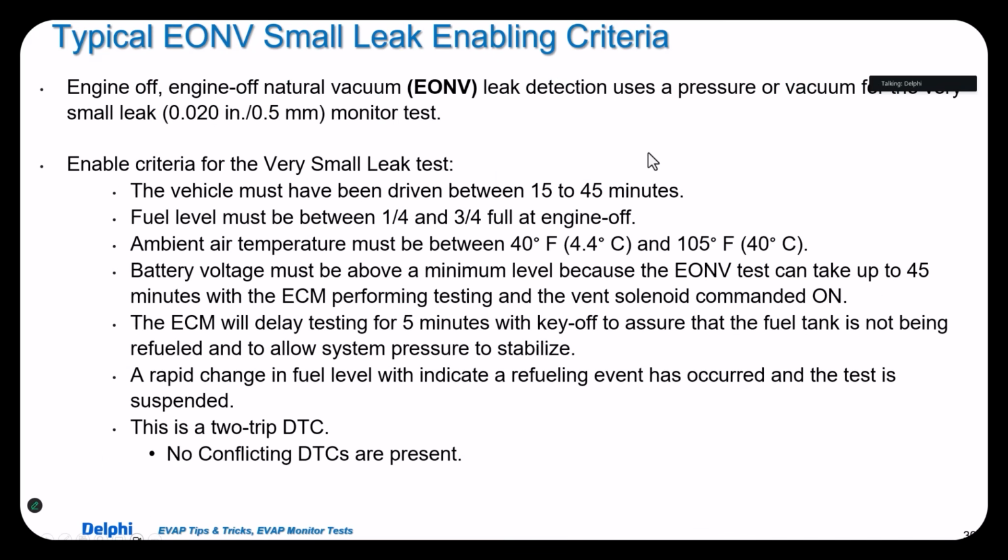Here's some basic criteria I pulled up. What you're going to find is most of these need, on average, about 15 to 20 miles of driving. I've seen it in miles, from 8 to 10 miles. The idea is if you're driving, the fuel is building, the tank is building pressure. If it's building pressure, now we're going to be able to test it. We're going to test it in pressure, we're going to test it in vacuum. So specifically, you'd have to look at each manufacturer, but unfortunately, many of them do a poor job of giving you these specs. Just know how it works, and you got to be patient.